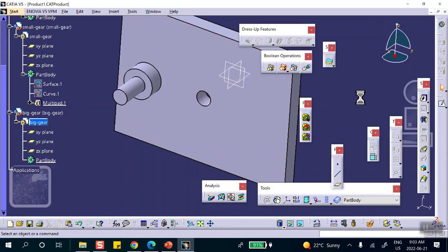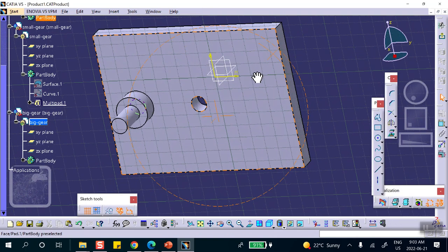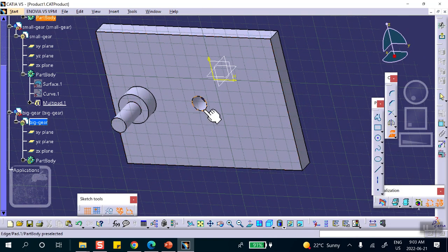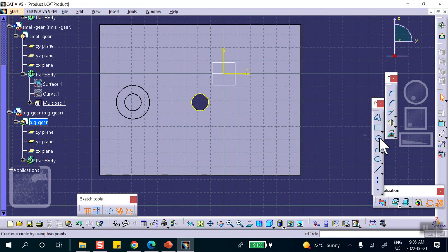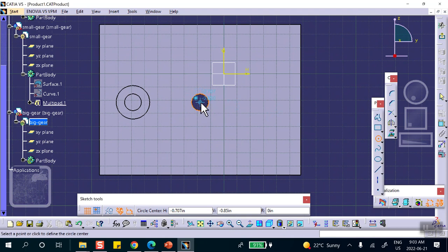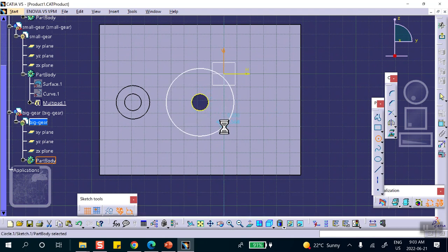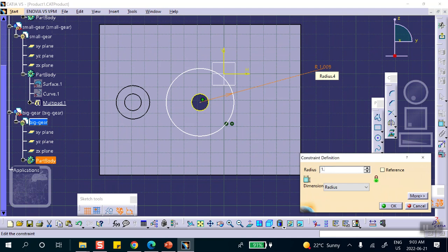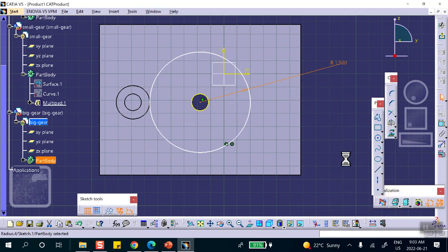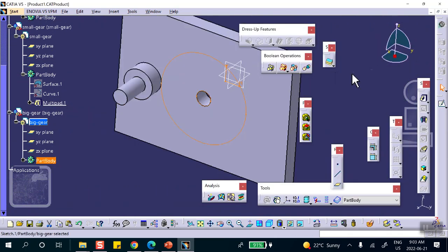Double click on it. On that plane, which is convenient for me, I will sketch. Why don't I project that circle? Okay, and normal view, and then draw another circle here. And the radius of this is going to be 1.5. One thing that's bothering me here, oh, there we are. Yeah, they should be touching, right? Okay, good. So exit. I thought they were not going to touch.